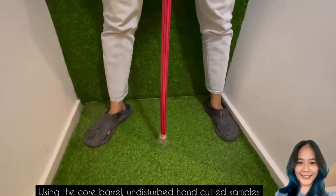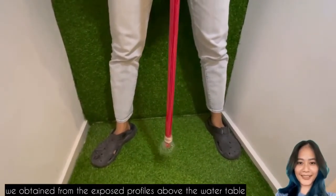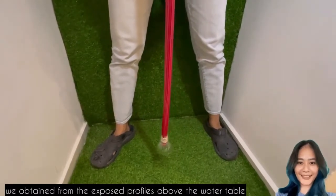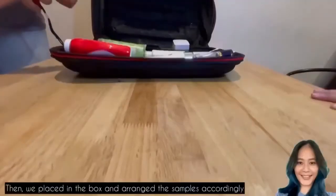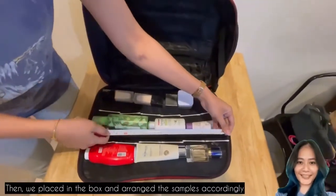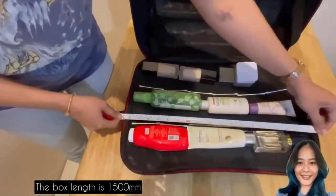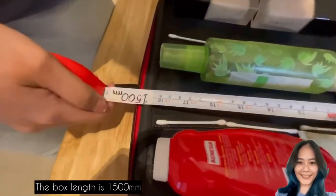Using the core barrel, we obtain undisturbed hand-cut samples from the exposed profiles above the water table. Then we place them in the box and arrange the samples accordingly. The box length is 1500 mm.